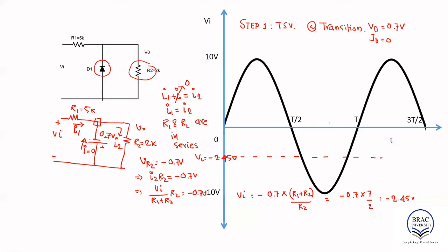So we already learned that if the diode appears to be in anti-clockwise direction, if you keep the signal to my left, in that case, for the values of the signal below the dotted line, or below the transition state line, the diode will be on. And the diode will be off above it.